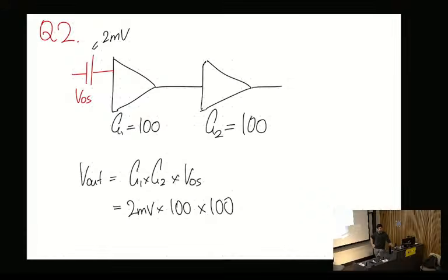So the noise floor on those amplifiers is quite low. It does mean to build those amplifiers, you have to sacrifice specifications in other areas, like maybe it doesn't have as high bandwidth. But the noise floor is very low on those amplifiers. Like for instance, neural signals, their value is like 40 microvolts. Like it's very, very tiny. So we have to use very low noise amplifiers to detect those signals. But yeah, so this is a problem, so we need to calibrate it away.